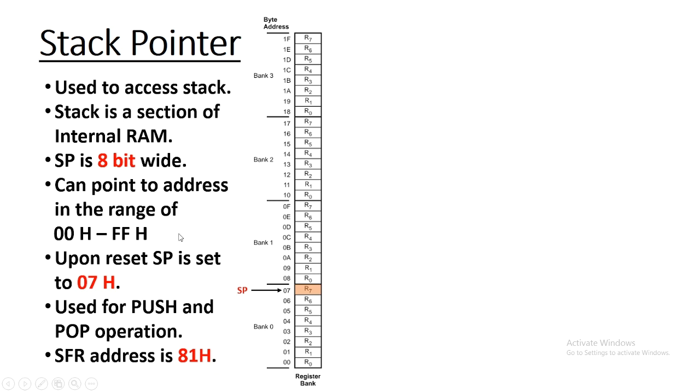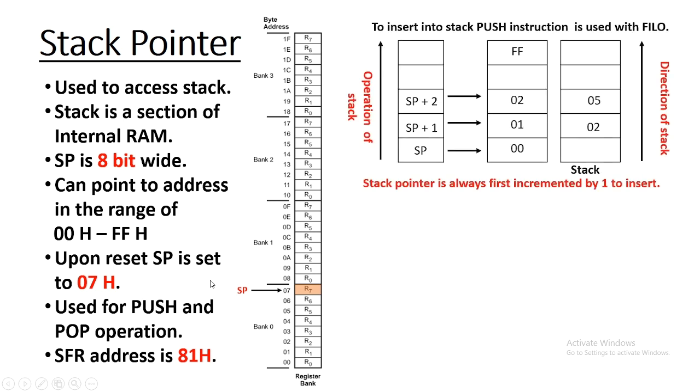So stack pointer is also an SFR register having address 81H. Any data is pushed onto the stack to save it temporarily and popped out of the stack to retrieve it. So the job of the stack pointer is very critical when push and pop actions are performed. Those two actions must be performed in pair.